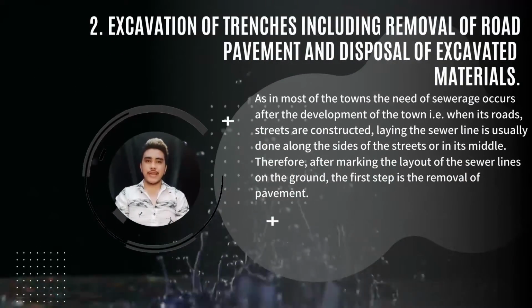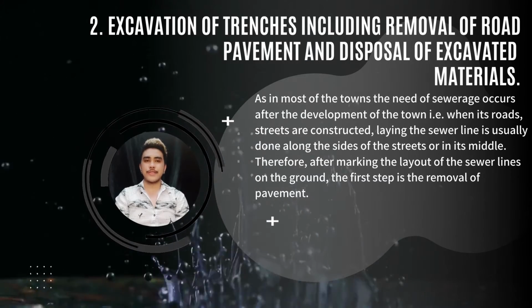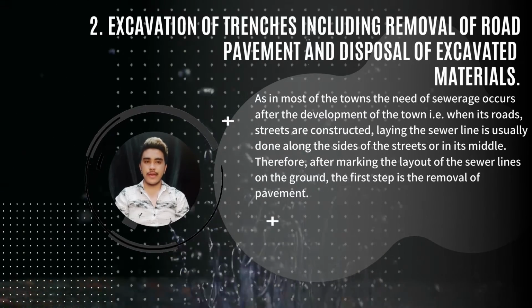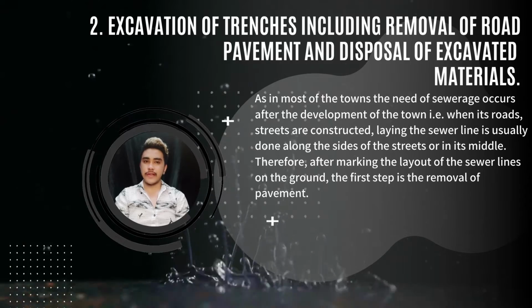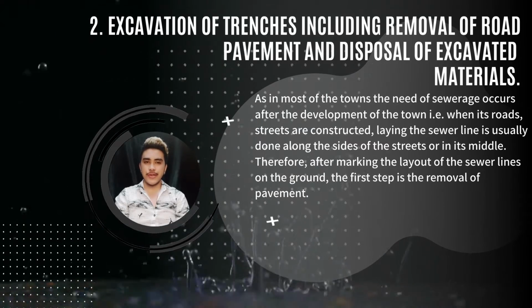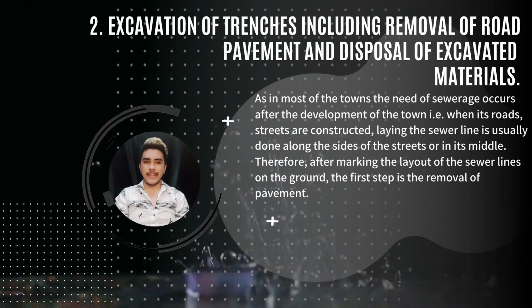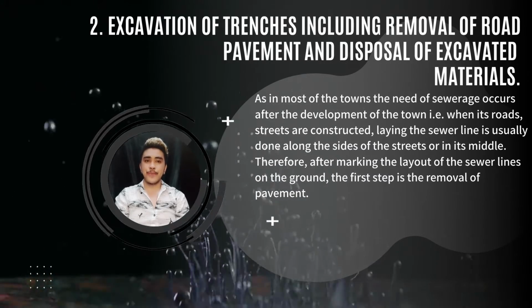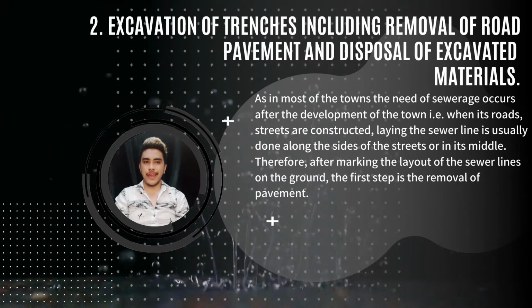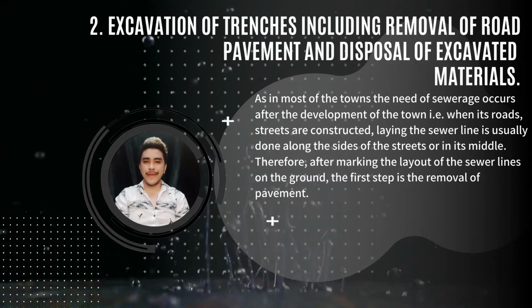Excavation of trenches, including removal of road pavement and disposal of excavated materials. As in most towns, the need of sewerage occurs after the development of the town. For example, when its roads and streets are constructed, laying the sewer line is usually done along the sides of the streets or in its middle. Therefore, after marking the layout of the sewer lines on the ground, the first step is the removal of pavement.